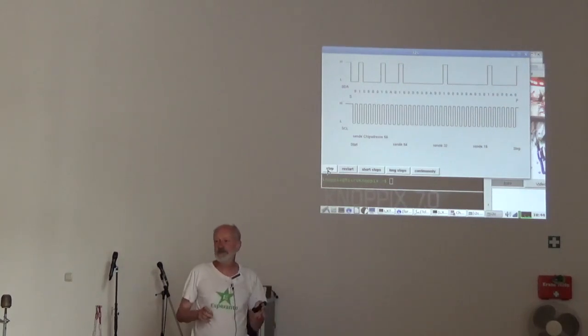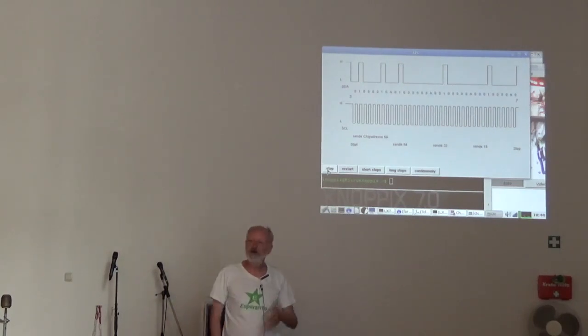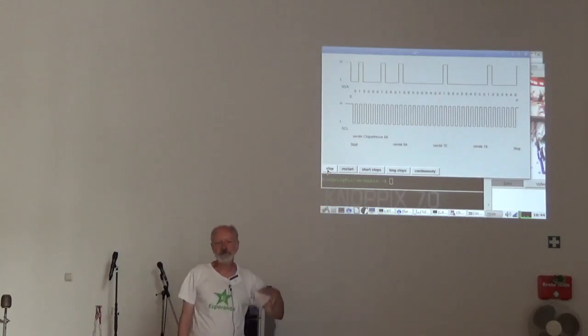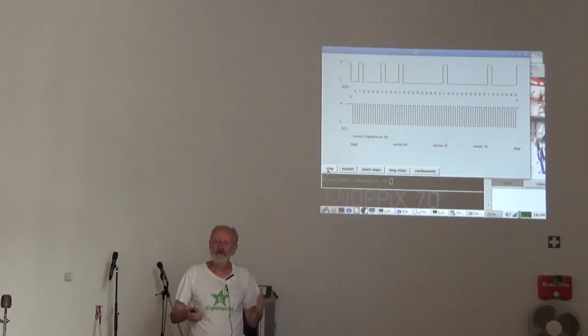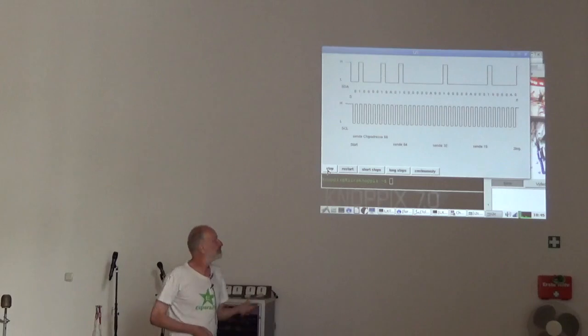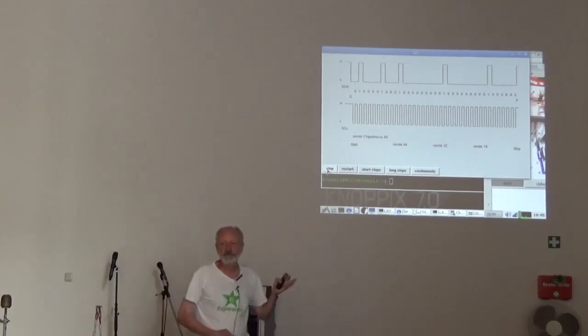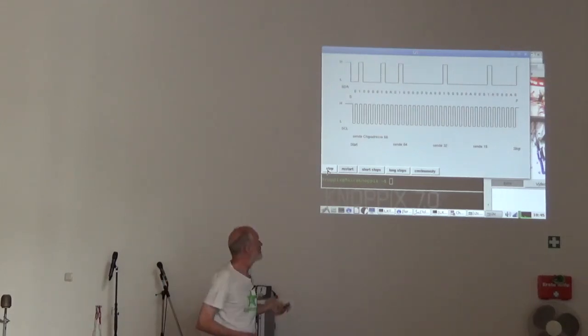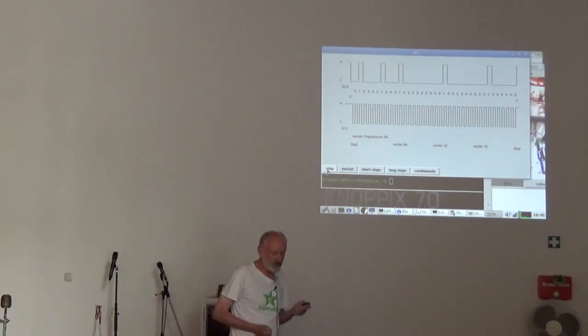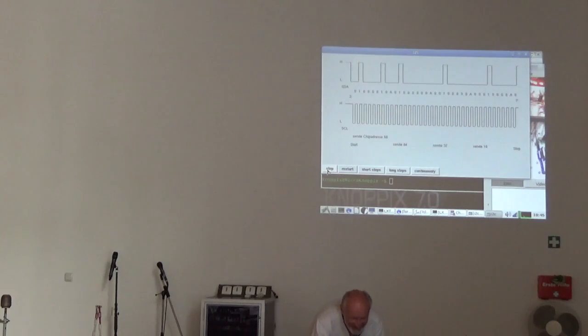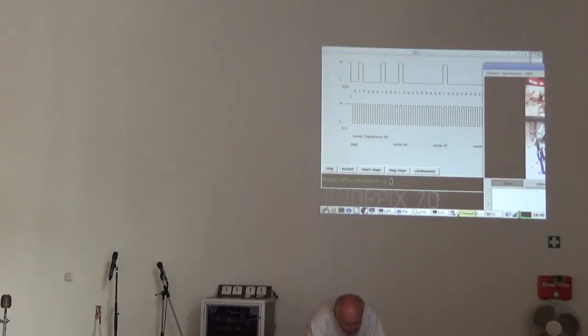In severe cases, I really have to power down the whole I2C bus and restart it, so that all the chips make a reset and the communication works okay. So, well, I hope you could see a bit how the I2C chip works. The next demonstration I want to show here is about